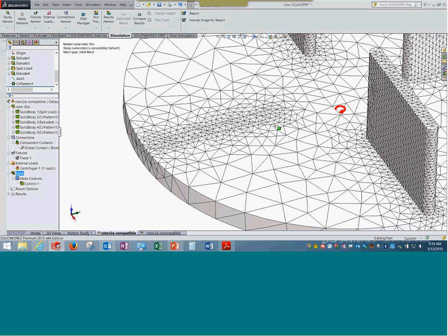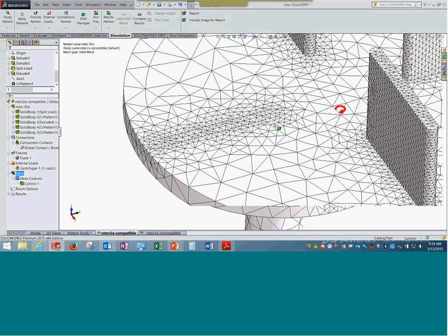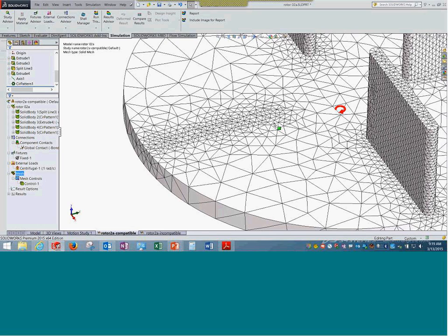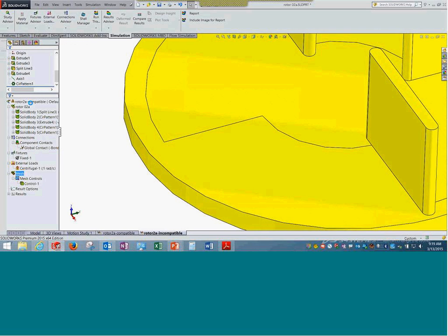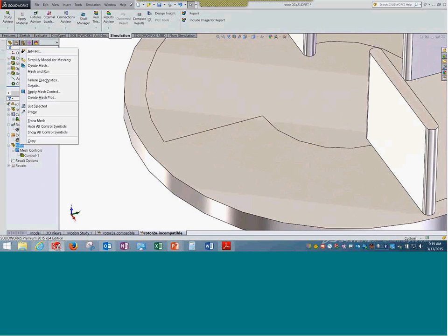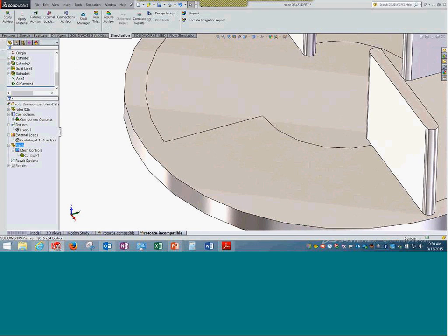These are cases wherein you will observe, if you try to mesh the parts separately, it meshes. When you take it to the assembly, it fails. And so in the assembly, if it is incompatible mesh, it meshes each of these parts separately as if there is no relation, and thereon it will create local connections at appropriate places. So quickly see this, if it is an incompatible mesh, what has been done or how it looks.